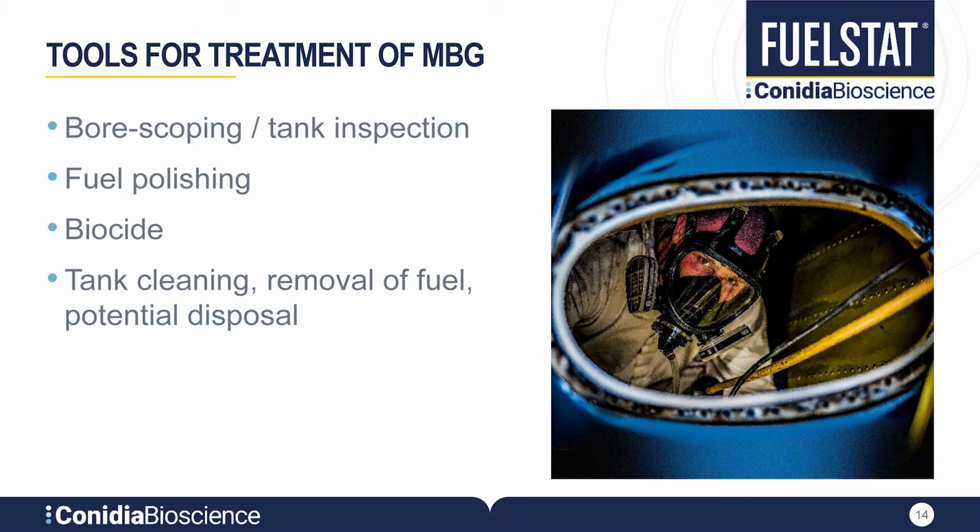We previously covered that not all organisms will degrade fuel, so why act upon a result that may have been influenced by outside sources, such as a technician handling a sample with dirty hands, or a fuel sample that was left unsealed and exposed to the environment for any amount of time? Having a look inside the tank for signs of contamination would be a logical and cost-effective place to start, potentially saving money in misdirected and remedial action or unwanted downtime.